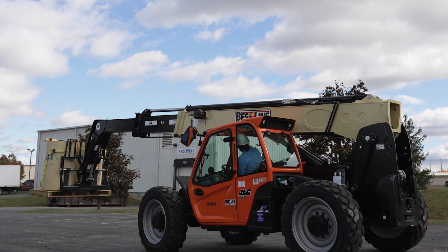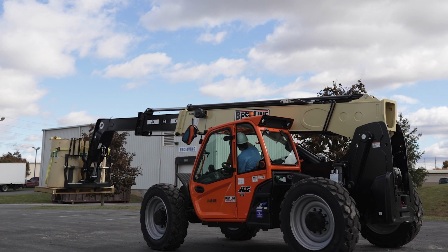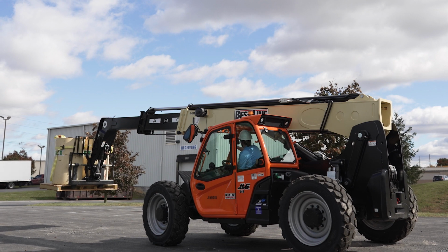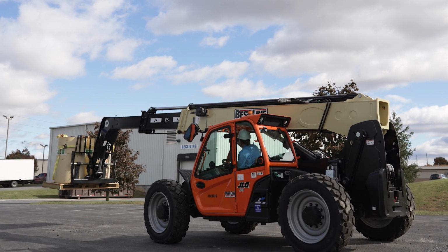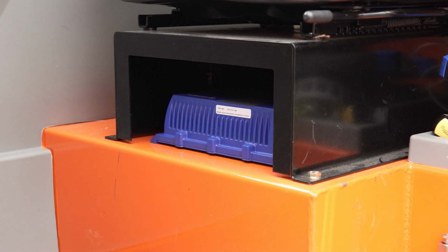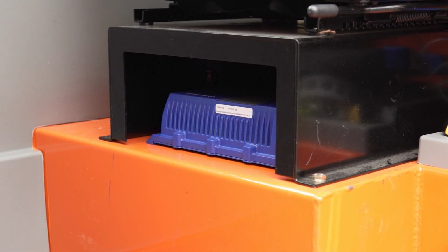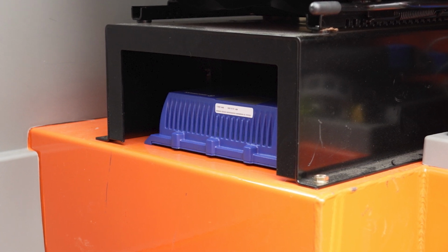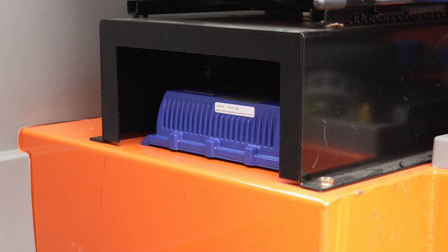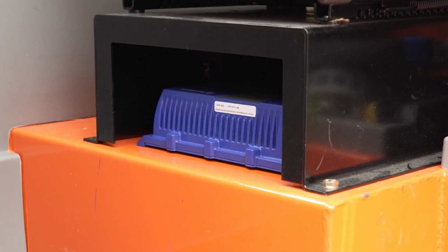If your machine has an optional motion shutdown from the manufacturer, the qSCALE I2TH RCI system can be upgraded to a rated capacity limiter by installing the optional cSCALE DIO module. With this functionality, the DIO module will send a signal when an RCL or LLML overload is triggered. This signal can be used with the motion shutdown to cut off the operator's ability to telescope out and boom down if the limit has been reached.